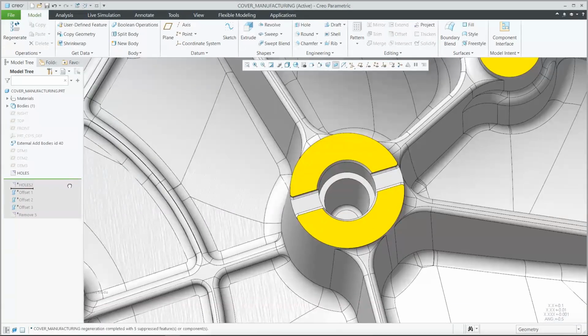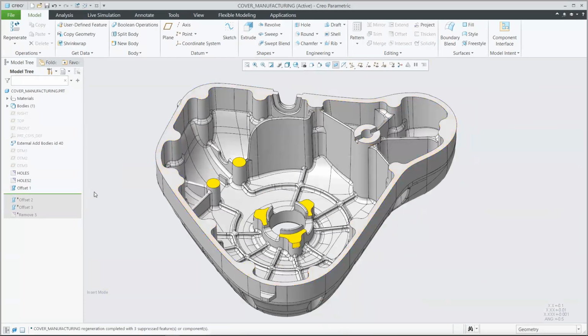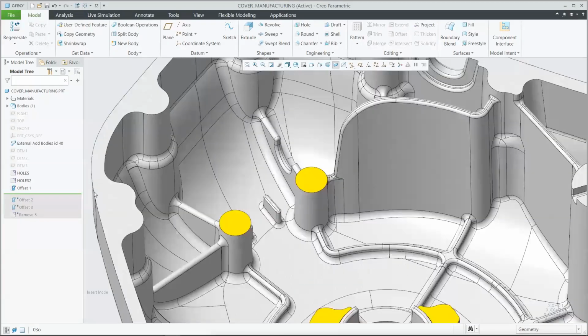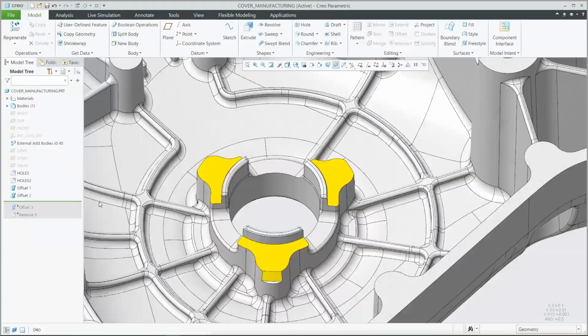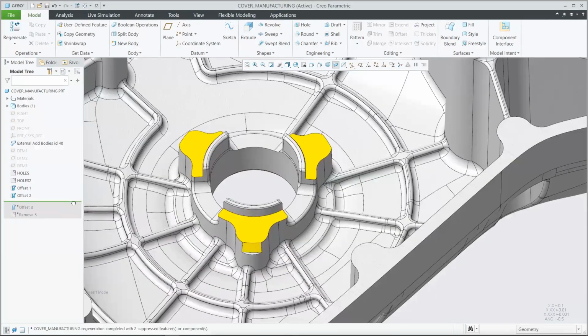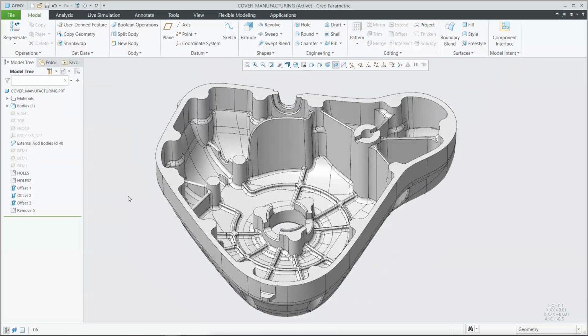And we see a lot of people doing this nowadays where they're using 3D printing to print out the main shape of what you're working with in terms of the model. And then from that point, you'd put it over onto a machining tool, maybe a 3-axis or a 5-axis mill, to go through and do some of the very precise edges where you want to get extremely low level detail. So what you're seeing here is essentially me rolling back some of the features that later on we might go through and machine off. That's just using some different flexible modeling capabilities. But again, we're just going to go through and work with the model that we're planning on 3D printing here.